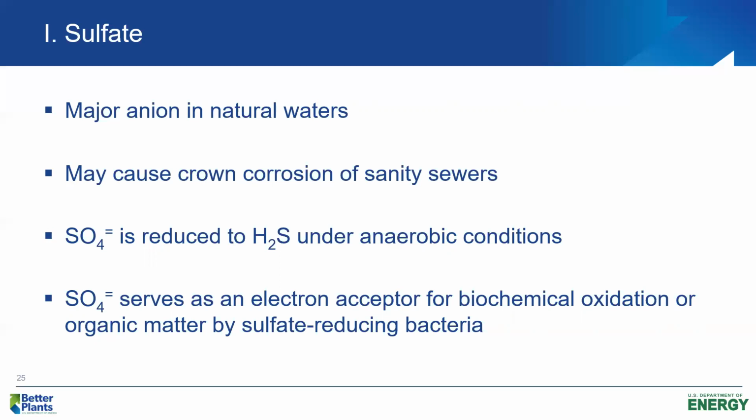And if it's a gravity concrete sewer and hydrogen sulfide builds up in the headspace, the hydrogen sulfide reacts with the moisture on the top of the concrete sewer, forms sulfuric acid, and that sulfuric acid will eat away at the concrete at the top of the sewer. That's what we call crown corrosion of a concrete sewer. So that's the problem in the sewer system.